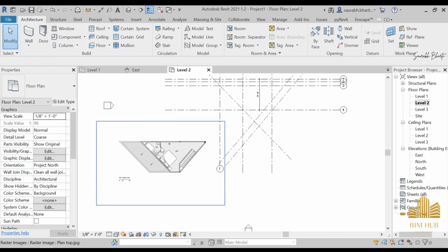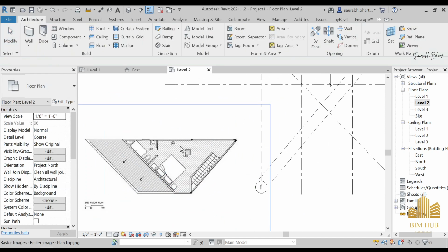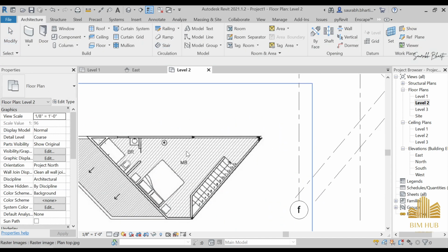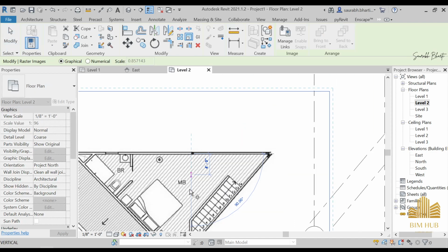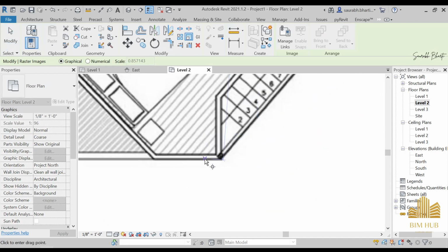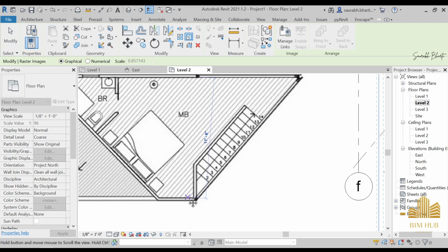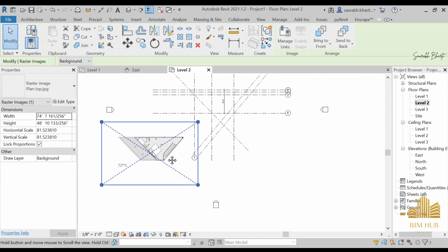So what we will do is RE resize, and now I will do the sizing without taking the distance, without taking the line. So just from here to here I will do it as 17 feet 9 inches. 17 feet. Okay, not 9 inches, 17 feet 10 inches.